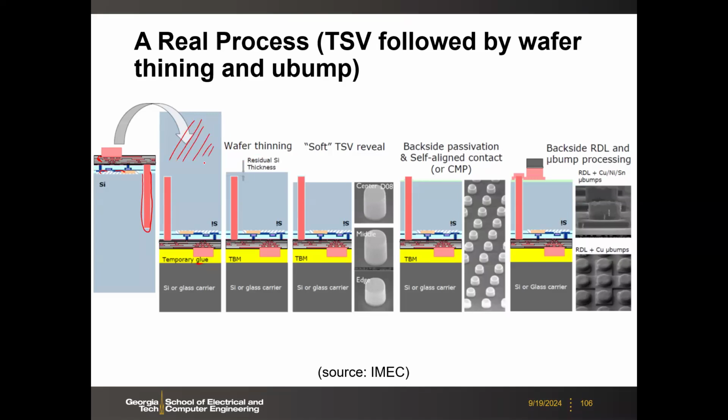You get rid of the additional silicon, thin down, and really make this trench exposed. And then you can have the bonding pad here. In this case, this is micro bump processing, so you add some micro bump material here. I believe this is the TSV in the middle. There are different kinds of process: TSV first, TSV last, and TSV in the middle. I will not go into the details because you have those packaging courses you can take.